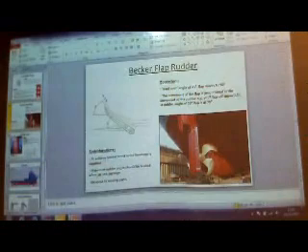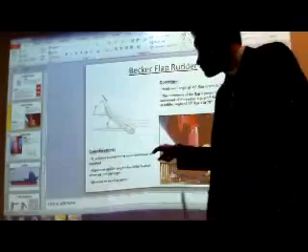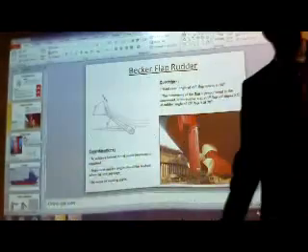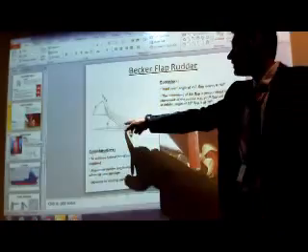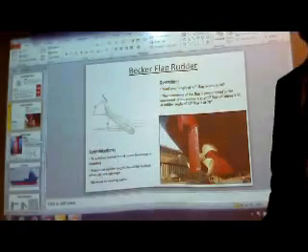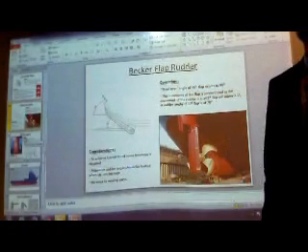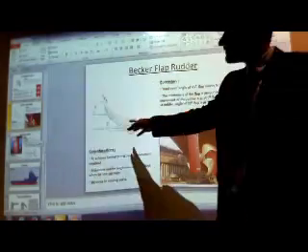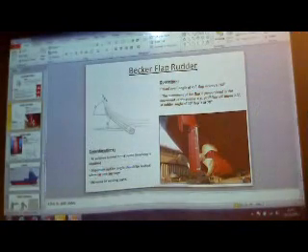To achieve lateral thrust, some headway is required. Maximum rudder angle should be limited when on sea passage. Because what will this cause? If you are at a very high speed and you start doing this, what will this result in? A great amount of strain, stress and drag on the rudder. Yes, vibration, stress. But this is designed for vessels which need higher maneuverability.